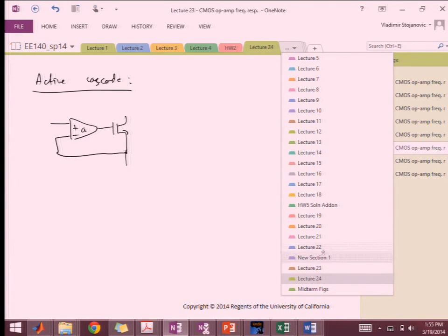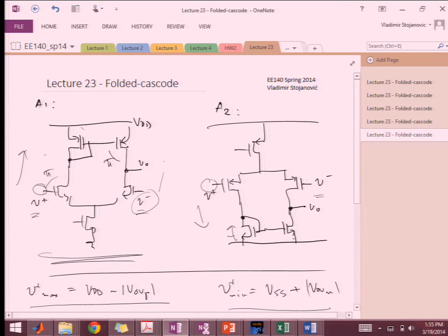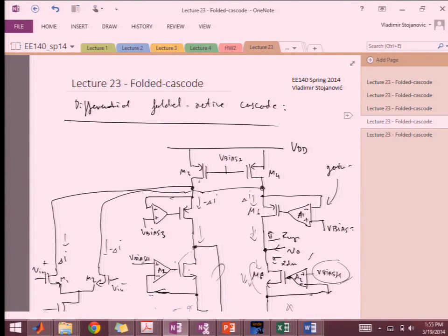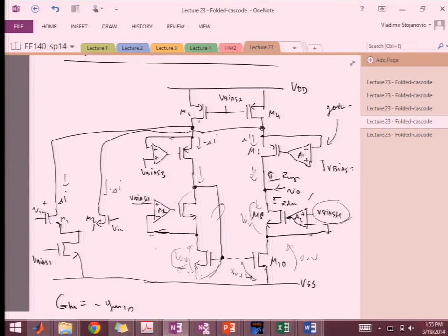That was lecture 23. Yeah, so these were the amplifiers, and we had this situation over here, right? And so each one of these guys actually has to be stabilized, because it can have 2 or 3 poles, or 1, 2 poles. Even if it's 2 poles, just from the mirror and then the dominant pole set by the output, you're still going to have to stabilize it in order not to have very low phase margin, right?